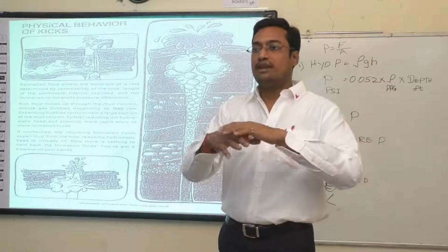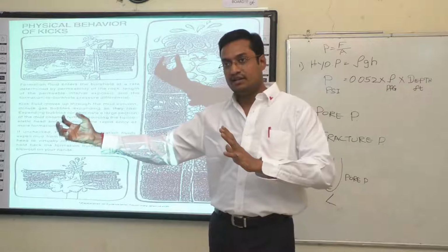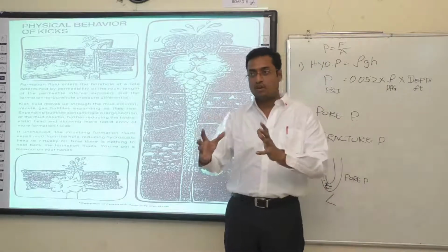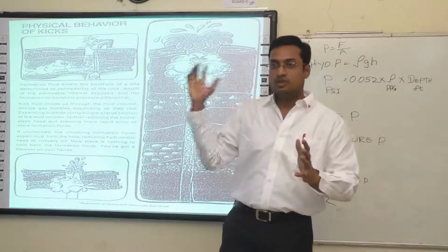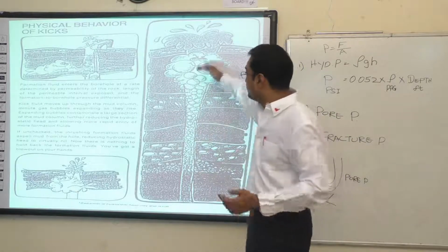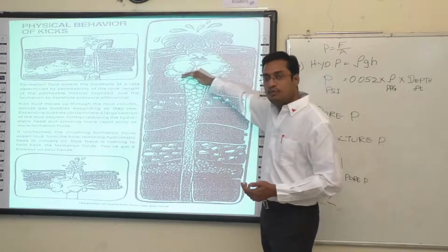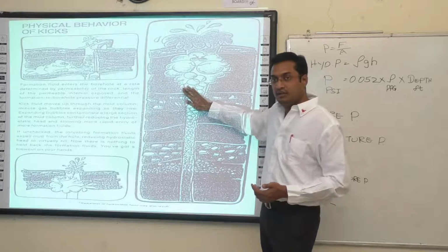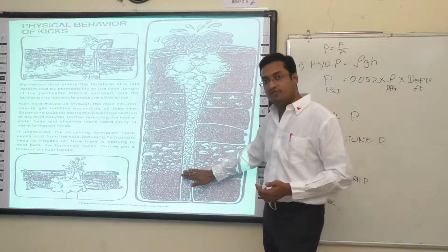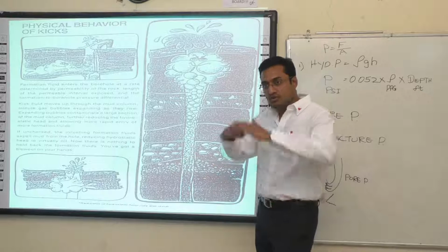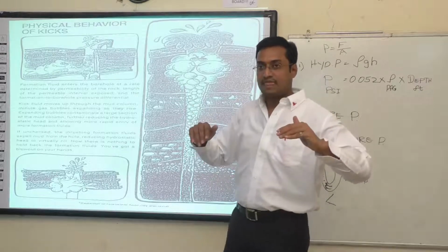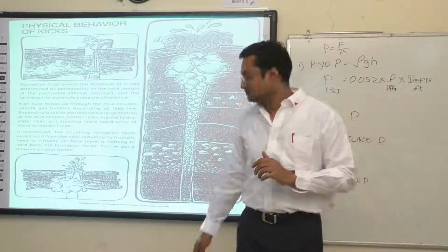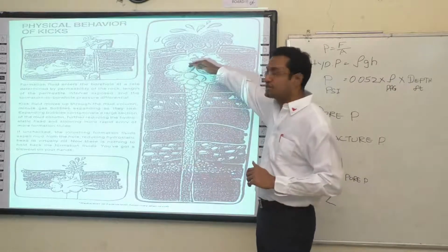So if you want to close the well, you need some equipment, a blowout preventer, BOP, which is a main component which will close the well. That is obvious. So if you use the BOP to close the well, you don't allow the kick to expand. You don't allow more entry of formation fluid. So you stabilize the well. You put a check, you put a control by closing at the surface.